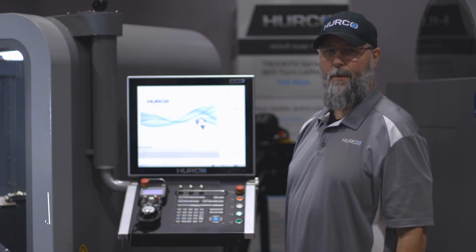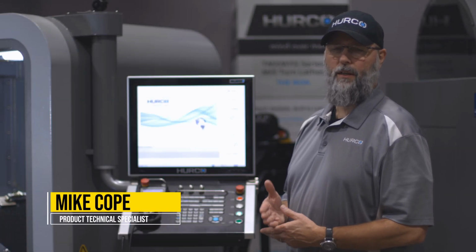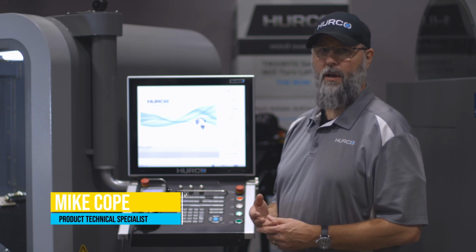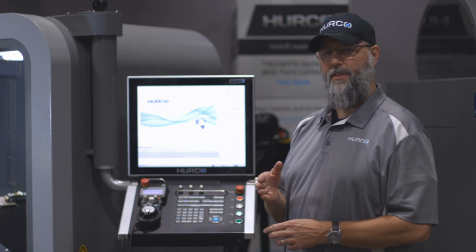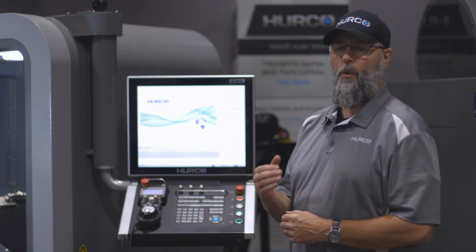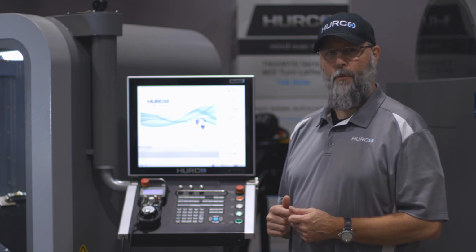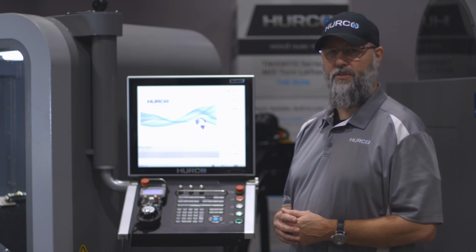So in this video, we're going to talk about how to create a master tool for touching off your tools. We use a master tool on a lathe when we don't have a presetter, the presetter is damaged or for some reason inoperable. So we're going to create this master tool that all of our other tools are going to reference. We're going to touch all the diameters off the same way on all the tools, including the master tool. The difference comes when we touch off in Z.